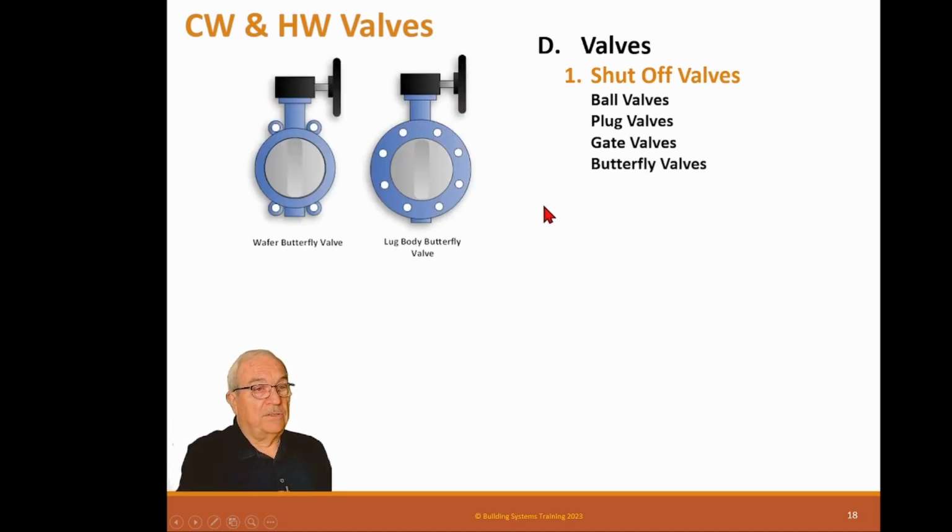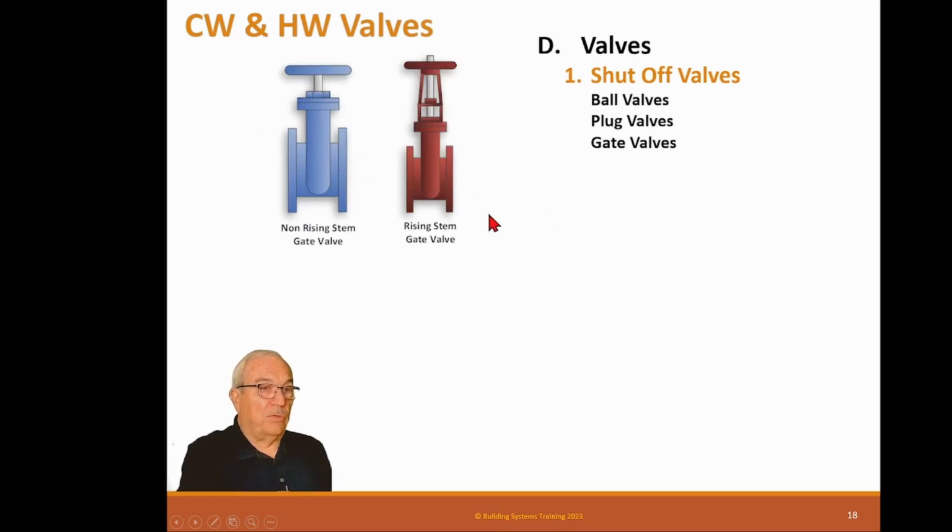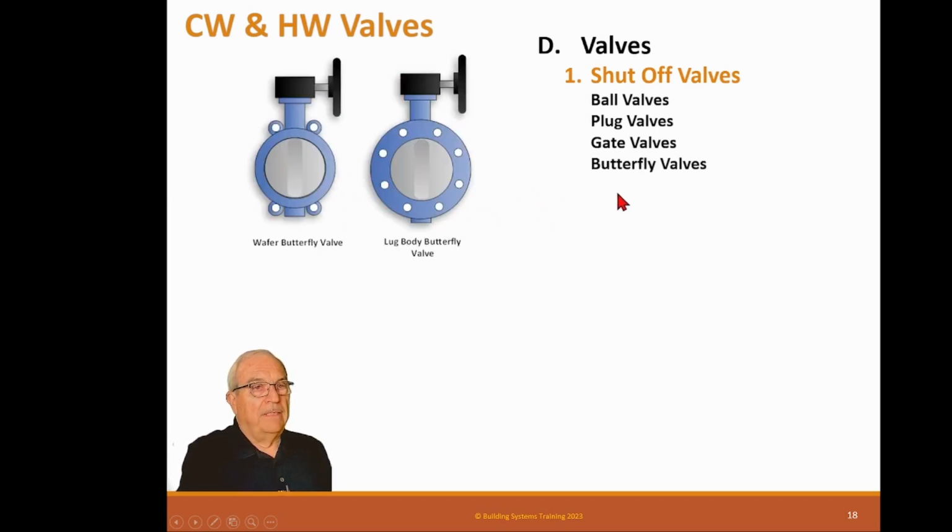Butterfly valves, so we've replaced these with ball valves and butterfly valves. Butterfly valves basically have a wafer, and when you open them, the wafer turns. So they're 90-degree valves. They rotate 90 degrees. Most of them come what's called bubble tight, so they'll have a rubber seat in here that it seals up against to get it to be bubble tight. In other words, it'll actually stop flow. They also make them that are not bubble tight, that are just a piece of steel up against a piece of steel, so they leak. You can't use them to shut off tight flow.